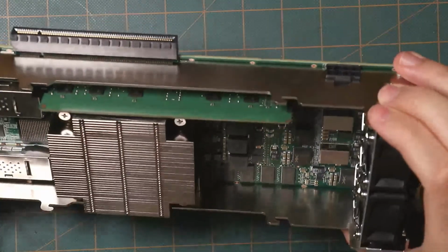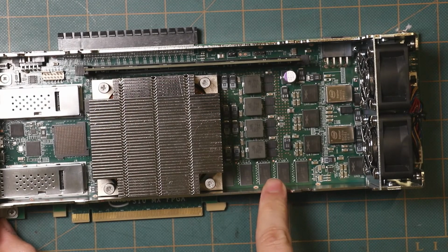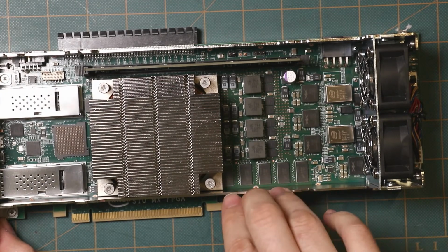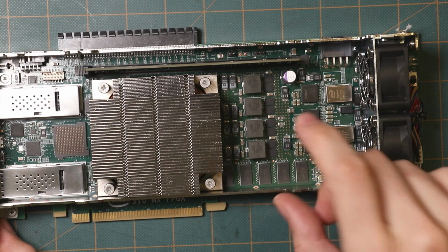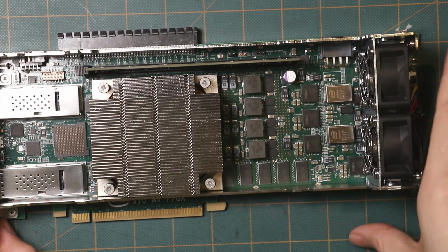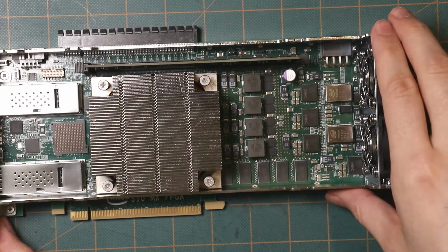It looks like, what is that, 5 chips? So usually the way they do this is it's a 72-bit interface, and they use 16-bit chips. So 4 of them will give you 64 bits, and then they use 8 bits on the last one to provide the ECC bits, basically. So that's pretty common. That's why you'll see 5 chips or 9 chips, because they're making a 72-bit interface.